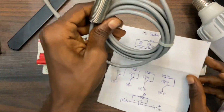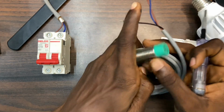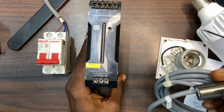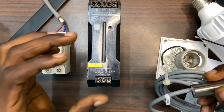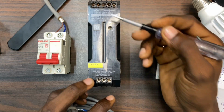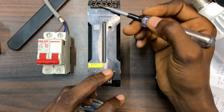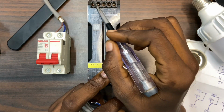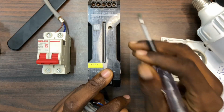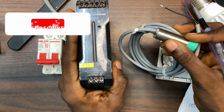This is a DC proximity sensor, and in order for us to use this DC proximity sensor, we are supposed to use SMPS. This is the SMPS. This SMPS you see here is what is going to help us convert the AC voltage to DC. We have the input here and the output, and with the input we have 3 terminals. This is the earth, this is the live, and this is the neutral. And the output, we have 5 terminals. You have 2 of them here as the positive and 3 of them here as the negative. So in order for us to use this DC proximity sensor, we have to use this SMPS.